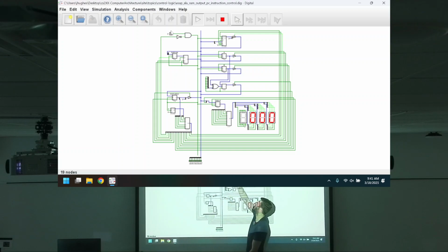What's fetch? Program counter out. That should start at a 0. Put it into there. 0's there. RAM out. Whatever's in address 0 goes into the instruction. Then steps 2 and 3. Fetch. Steps 2 and 3. Whatever that means. It's a no-op, so nothing's going to happen.